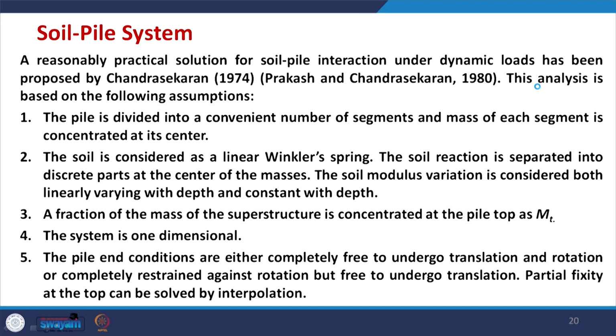So, let us first talk about the soil pile system which needs to be considered. A reasonably practical solution for soil pile interaction under dynamic loads was proposed by Chandrasekharan in 1974, and that was later published as Prakash and Chandrasekharan in 1980, and this analysis is based on the following assumptions. What are the assumptions? The pile is divided into a convenient number of segments and the mass of each segment is concentrated at its center. So, let me show you this slide.